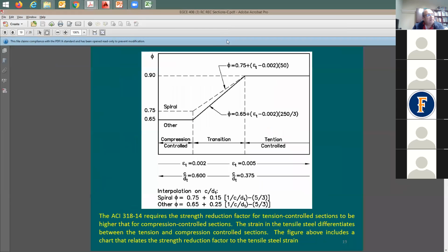Do you remember this chart? Oh, okay, yeah, now I know. Now, how much is C over D according to this? You see this? 0.07. Wow, it's very small. Is it giving this side or that side? The left or the right? To the right. So it's going to be here, so phi of 0.9. Okay. Very good.